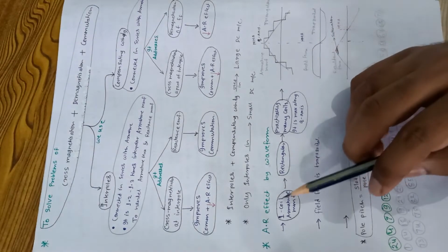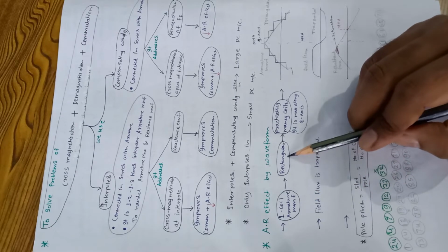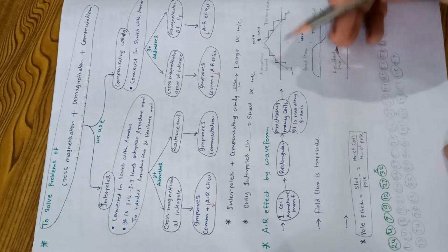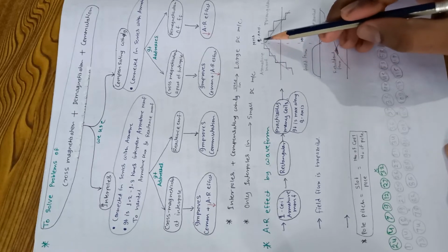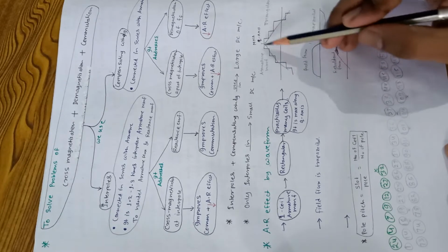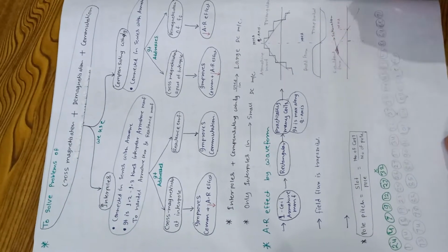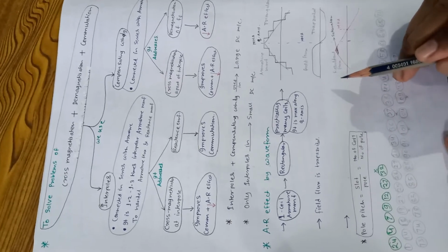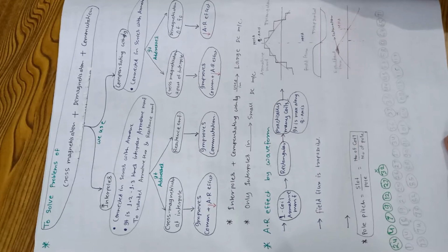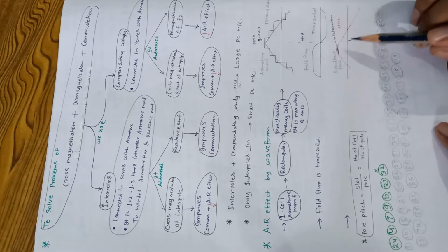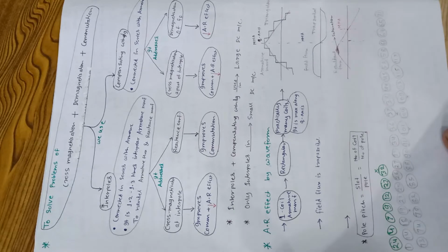When we talk about armature reaction effect, a single coil's armature MMF is rectangular, but practically many coils are there, so due to many coils we have an overall triangular shape. The field flux is trapezoidal, and the induced EMF is trapezoidal AC. The resultant flux is also triangular, we can say.